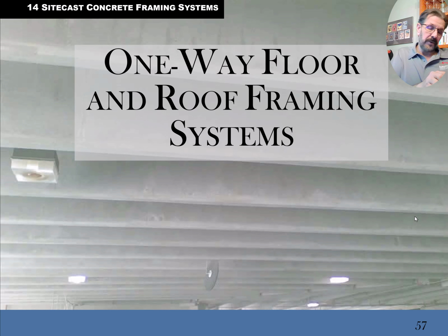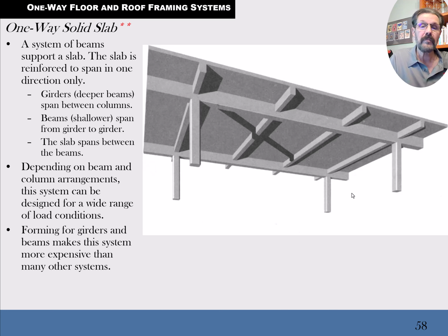Now there's another system here of 1-way and 2-way floor systems. A 1-way floor system is where you've got these long, narrow bays. Right here, we're looking at a bunch of ribs, and these are acting like joists, so that's a 1-way floor system. Now, if you've got a rectangular bay between the beams and joists that's more than twice as long as it is wide,